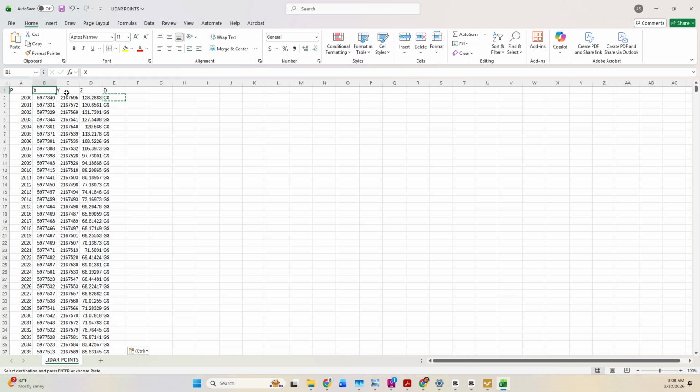N is northern because we're positive on the y-axis. So that's why it's north. PENZD, not PNEZD. So you can switch it, or you can import as PENZD.